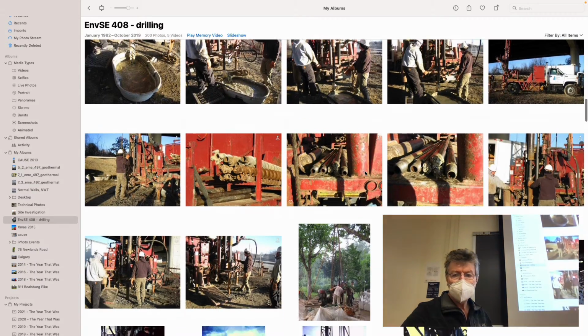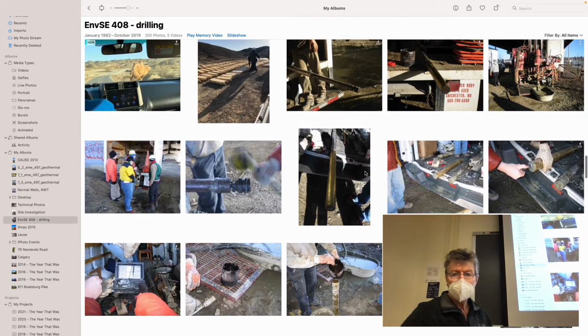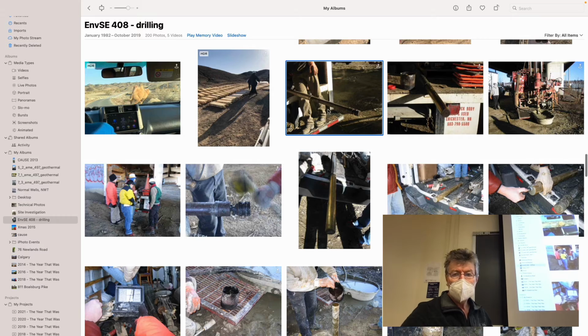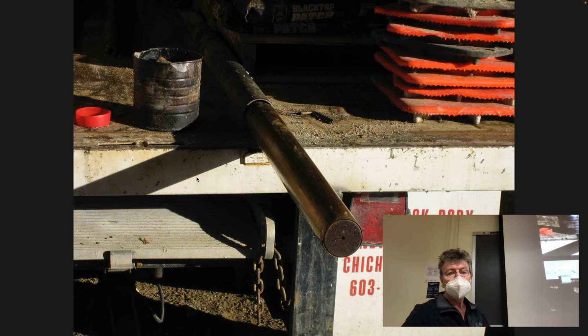What did we look at? Yeah, we looked at all of these. So we're specifically going to talk about sampling. So this is kind of where we left off. So this is exactly what we talked about. This is a piston sampler. So this is the piston that goes on the thin wall sampling tube. It exists along the length of the tube, and it's advanced along the length. You can activate it from the surface once it's deployed into the bottom of the hole.